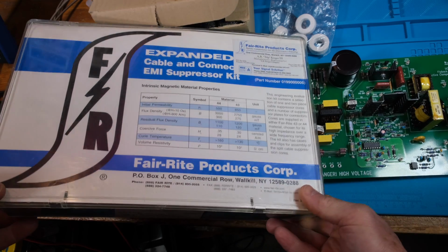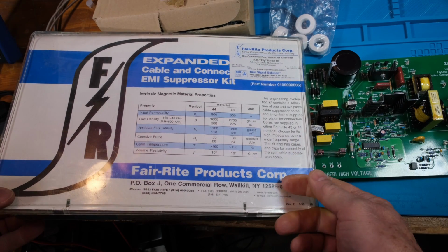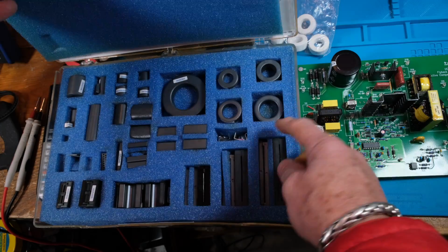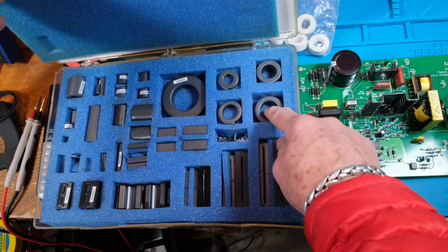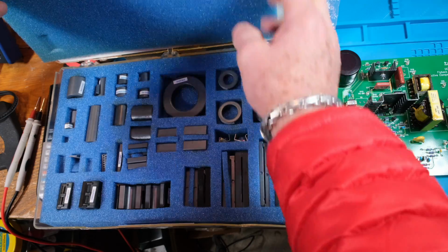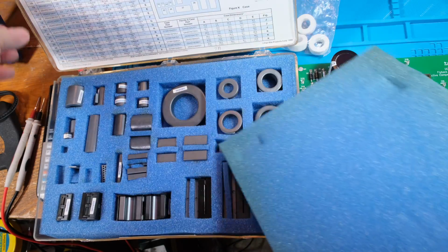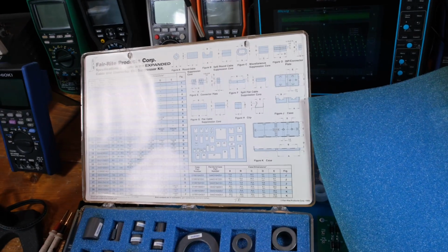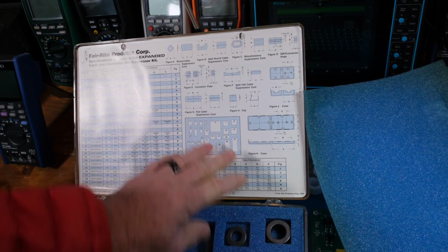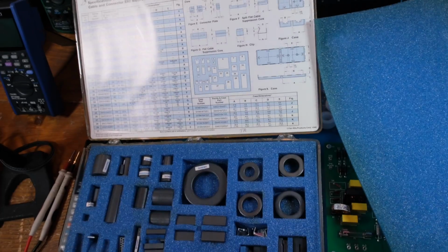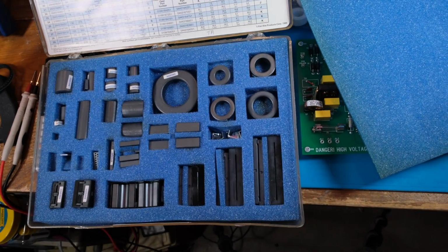Now, guys, you might be able to get a hold of some kits for EMI designing, and this one might not be the right one, but it looks something like this. And you get these cores, and they would have some information about them, like in the lid, right up there. And if it was really meant for a common mode choke, you'd see these curves, impedance curves and stuff, which I'm going to show you.